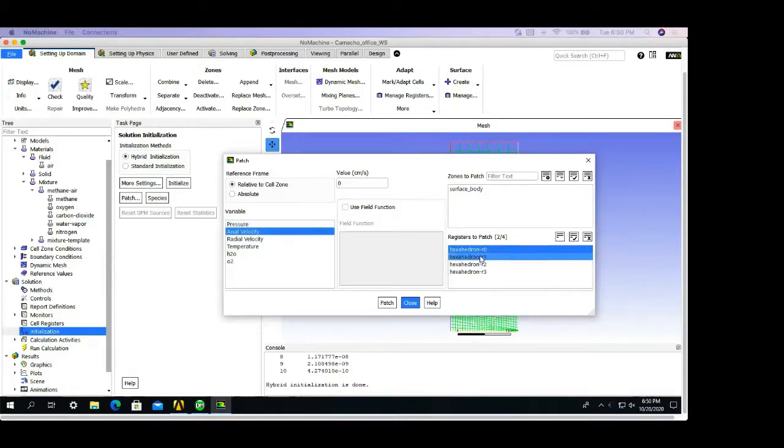Then similarly for the sheath, we know what the temperature of the incoming gases is, we know what the concentration is, and we know what the velocity is. So those are the typical things we input. Then if you go to the flame zone, from our OpDiff calculation, we know what the flame temperature is. And we can give an initial guess for some radicals like hydrogen, oxygen, hydroxyl, and we also do argon, which is a major species for us. So for some of those major species, we give an initial guess.